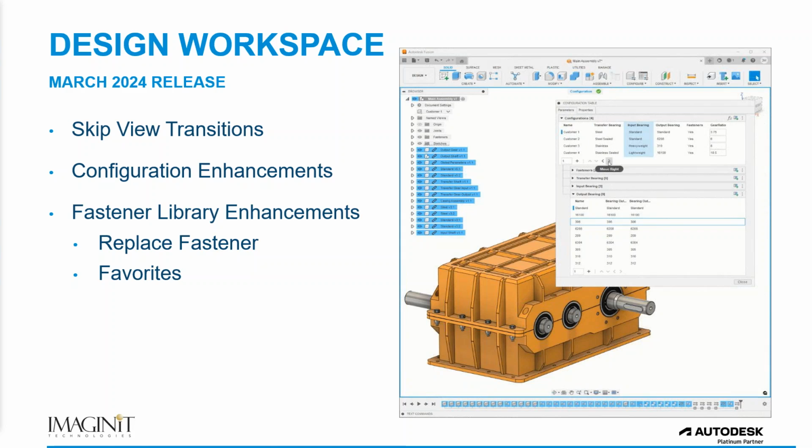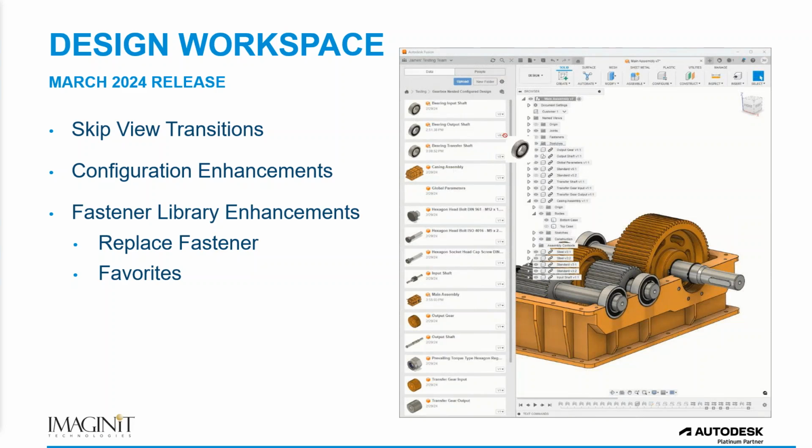Moving on to the design workspace for the March release. There's a few things here of note. One is the skip view transitions. If you're using the view cube or named views, when you pick on one of the faces of the cube or you initiate one of your named views, the default behavior is to rotate the part around. You get an animation as the part moves in that lowest energy rotation to get there. There's now a setting though that we can turn that off. And so that's the skip view transitions.